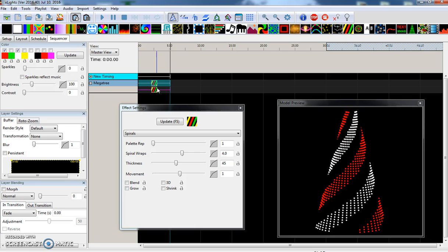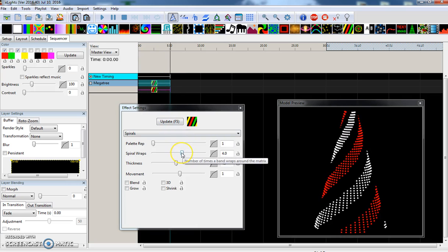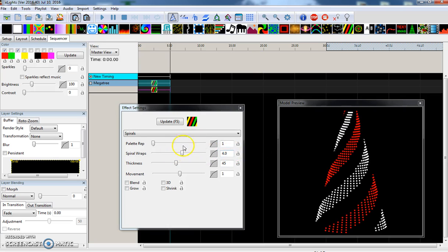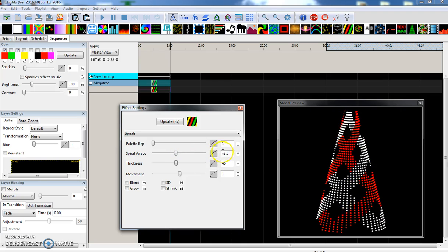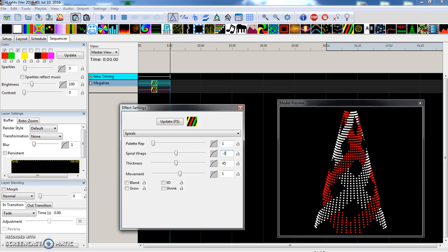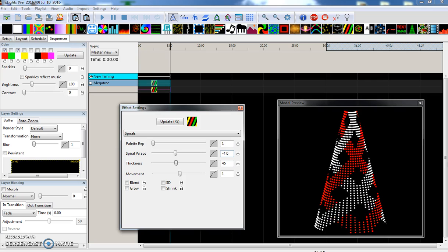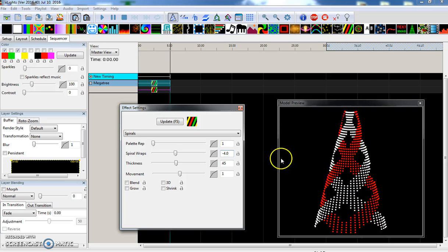To get the diamonds, you first take the spiral wraps and you want to go to a negative number with the same value. So it's +4, we're going to change that to -4. And visually you should see a plaid type pattern if you have the mask type set to normal, which we do on the bottom left corner. I'm going to type this in -4.0. Some people think that right there looks good. I think so.